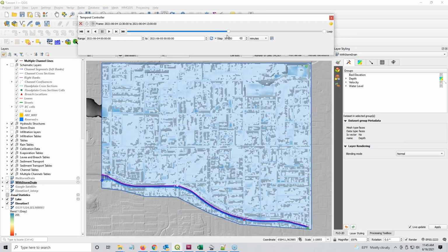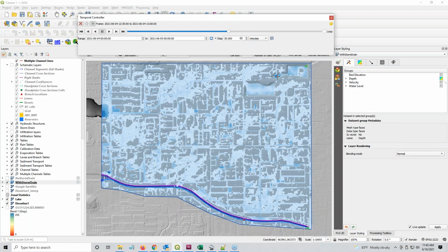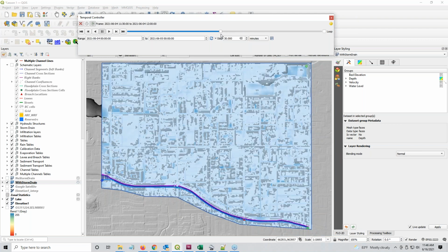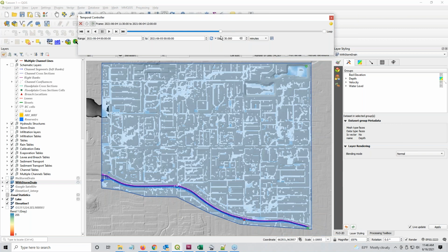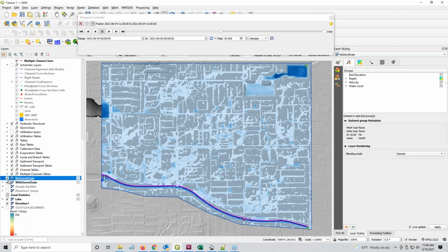And you can see that we're not getting that overtopping of this basin because my head wall is turned on and active and sharing between the two basins. So that's one way that you can use it to make comparisons between the two, and you can see changes in the water, and the time is the same for both layers.